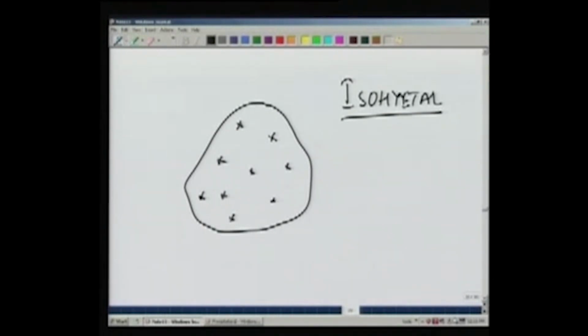So if we have the precipitation values at all these stations, we could look at those values, and using those values we could draw isohyetal lines. For example, this rain gauge, this may be 8 millimeters, 10, 12, depending on the values of these rain gauges. So all these rain gauges will have values between 8 and 10.